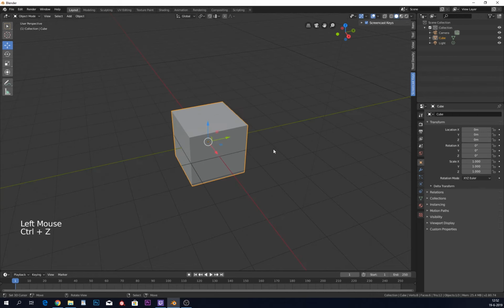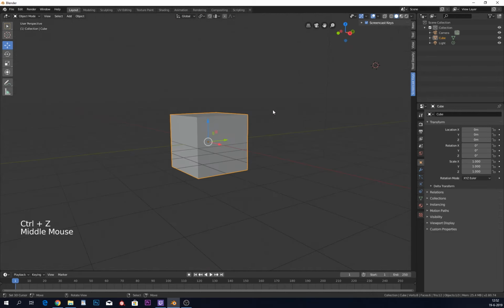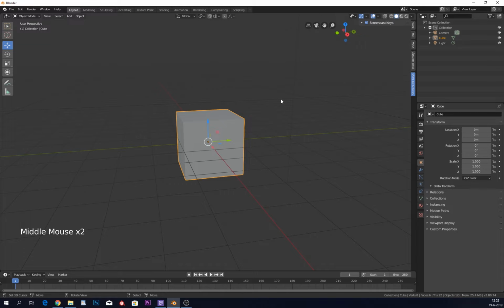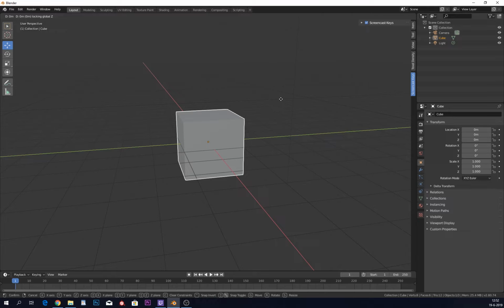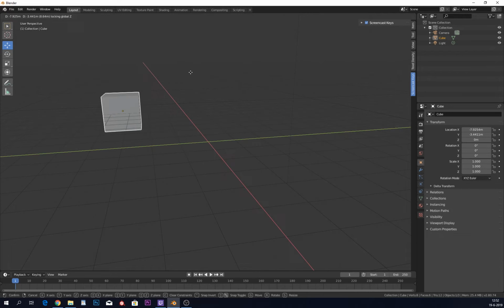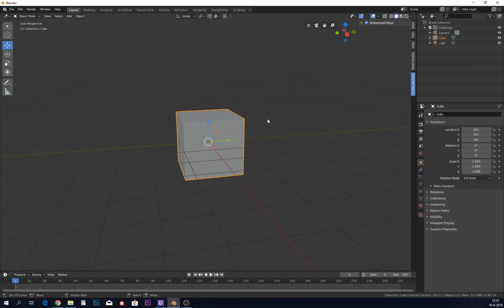So let's say right now we also want to exclude something, just like the plane here. We want to move it around every axis except the Z axis. So now it is G Shift Z. And you can see that the Z axis is not lit up, but the other two are. So now we can move around everything. So the shift essentially just says don't go around the Z axis, right? Do not go around the Z axis. Cool. So that is our moving. G Shift Z.